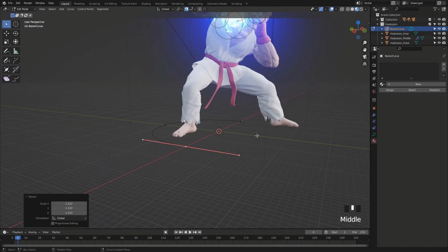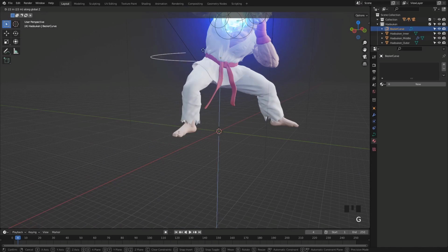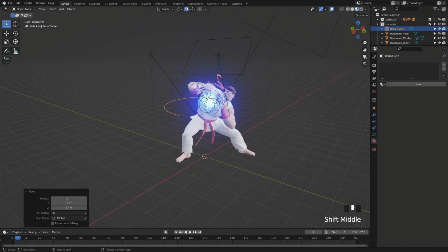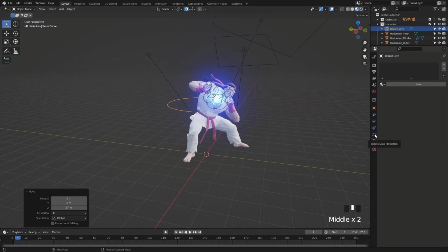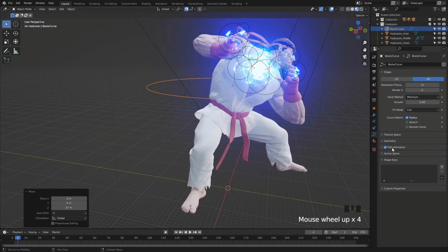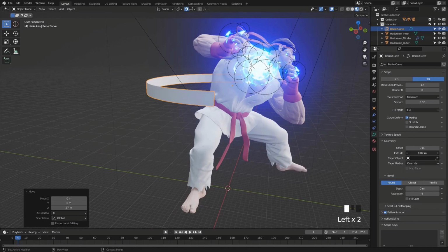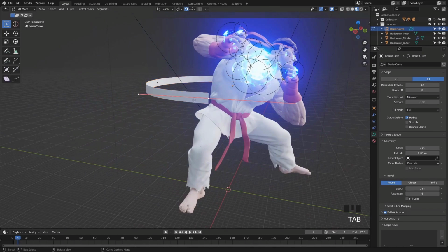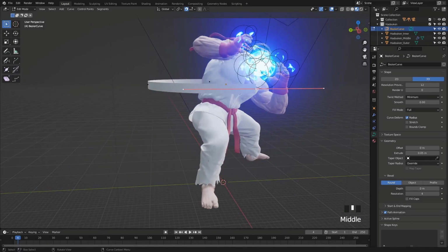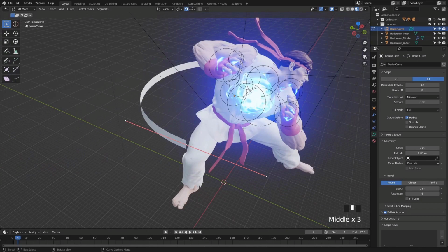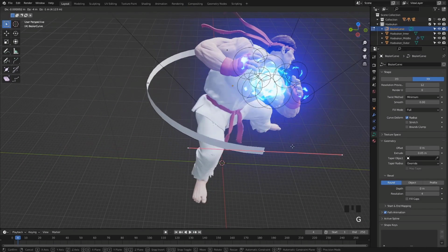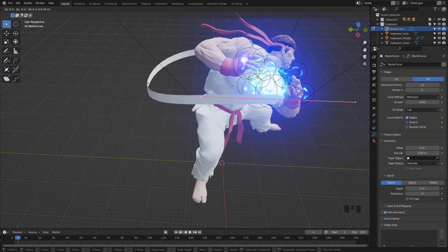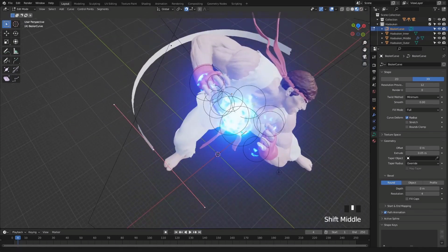So let's go ahead and get started with the look of this curve to make it look like it's a streak of wind. What we can get started with is coming over to the object data properties of this spline. We'll go over to the geometry tab and then turn on the extrusion. As soon as we do, you can notice that the extrusion is working to make a kind of card. So basically the spline is being extruded up and down. If we go into edit mode, we can see the center of the spline is right in the middle. This lets us affect anything that we want. So now if we start moving it, you can see it starts updating the extrusion we made. So it basically looks like a card or a ribbon, and that's what we'll be using for this specifically.